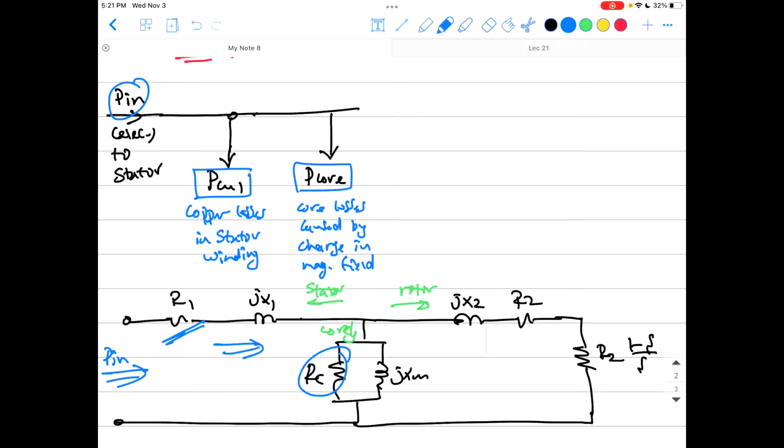Okay, but those are the lumped core losses in the stator and rotor together. So the core losses here are the losses of the whole core, which is the stator core and the rotor core lumped together. Okay, and like we said before, we know the core losses by experimental work, and most of the time they come from empirical formulas, so it's just something we can play around with.